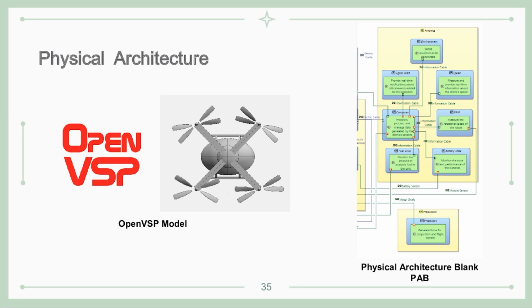All this data is then sent to the ground station through the communication subsystems. And the propulsion subsystem, for this subsystem, we use tools such as OpenVSP, which allows us to create aerodynamic models of the drone. And after testing various configurations, we determined that a quadcopter design was the most efficient. Additionally, simulations in MATLAB demonstrate that a coaxial configuration will be the most suitable, as it increases the propulsive disk area and serves as a constant backup in case of rotor failures.